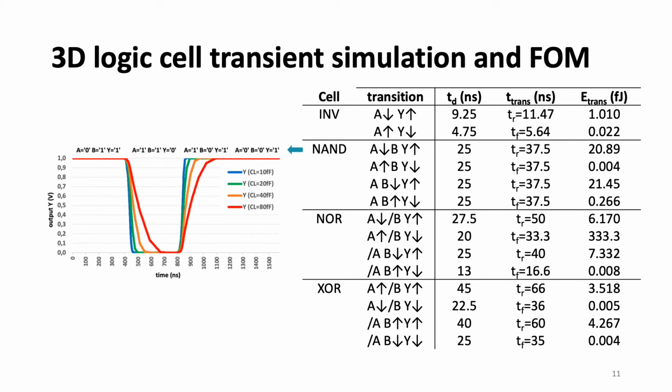The table on the right shows the simulation-based measurements of typical performance characteristics of the library of logic gates using typical measurement conventions for delay, transition times, and transition energy.